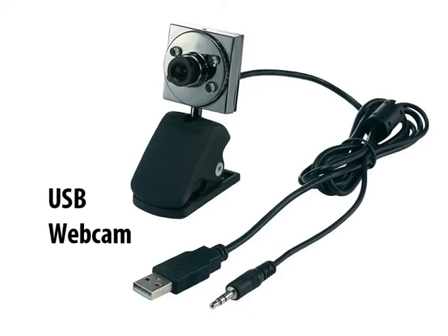A physical USB device may consist of several logical subdevices that are referred to as device functions. A single device may provide several functions. For example, a webcam video device function with a built-in microphone audio device function. Such a device is called a composite device.